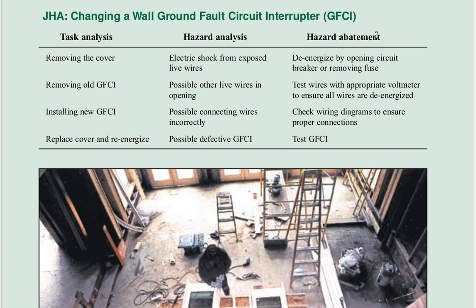Now, this 5 milliamps or more that is missing from the current coming back in could possibly be flowing through a defective tool, through somebody's hand, through their body, and down back to earth. So that is why the GFCI protects you from getting an electric shock.